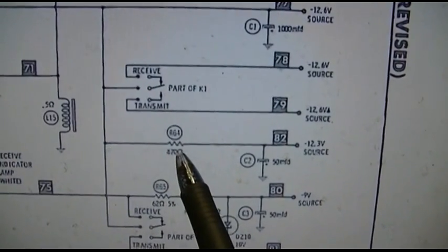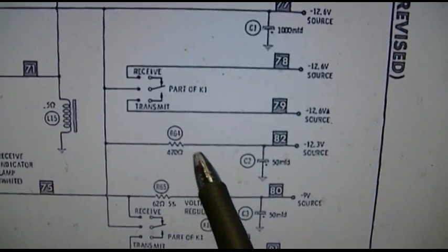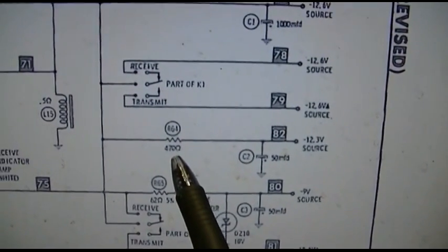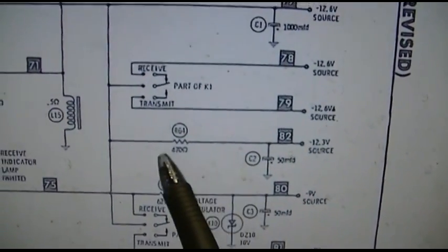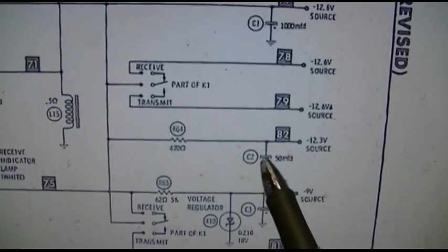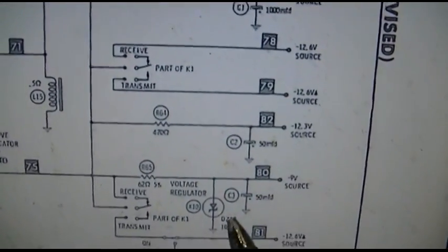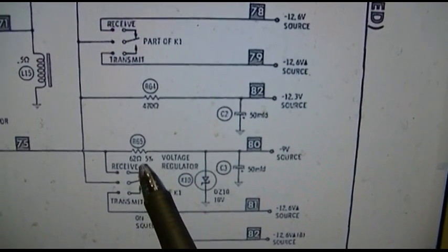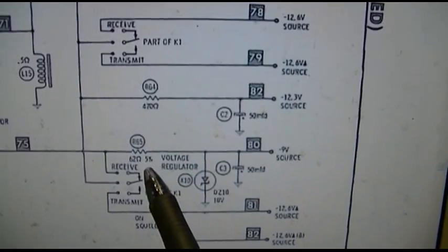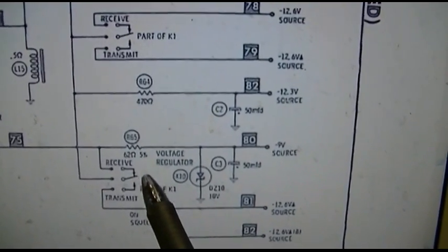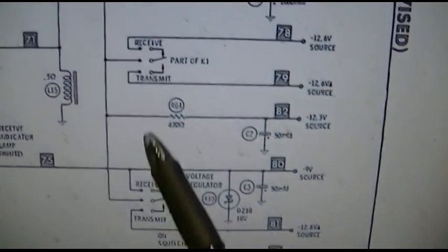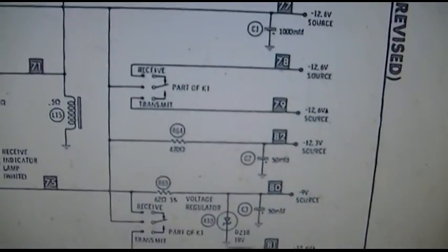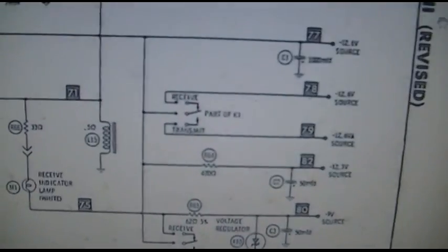And then for instance here you have a resistor. Well, you know that if it's drawing 5 amps and that's a 400 ohm resistor, it's not possible, unless the resistor is shorted, so you could eliminate this. And again here you have a 62 ohm resistor, which you're not really going to get 5 amps through without this burning up. So with the relay eliminated, you can eliminate all but just this line without touching any of this stuff.